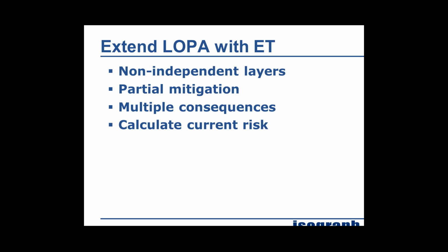The event tree, again, coupled with fault tree and using this quantitative methodology, can calculate our current risk level, very similar to how we would do with a traditional LOPA, and also helps us figure out what we can do to lower that risk. Suppose we're given a reliability target that we're supposed to meet. It can help us figure out how far off we are from the goal or if we're meeting it. And coupled with fault tree methods like importance analysis, it can help us figure out where to focus our efforts to lower that risk.